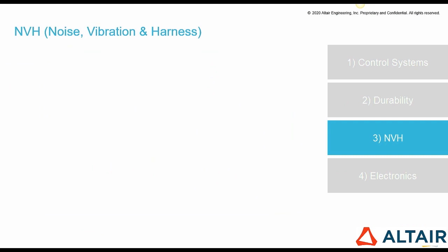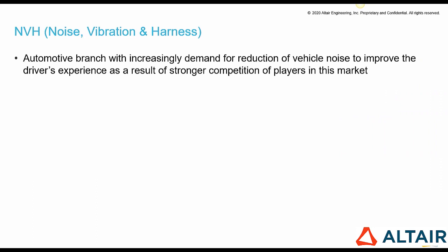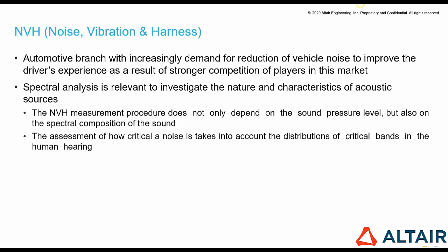Let's talk about NVH and signal processing now. So NVH has become an automotive branch with increasingly demand for reduction of vehicle noise to improve the driver's experience as a result of stronger competition of players in this market. And moreover, spectral analysis is relevant to investigate the nature and characteristics of acoustic sources, because the NVH measurement procedure does not only depend on the sound pressure level, but also on the spectral composition of the sound.